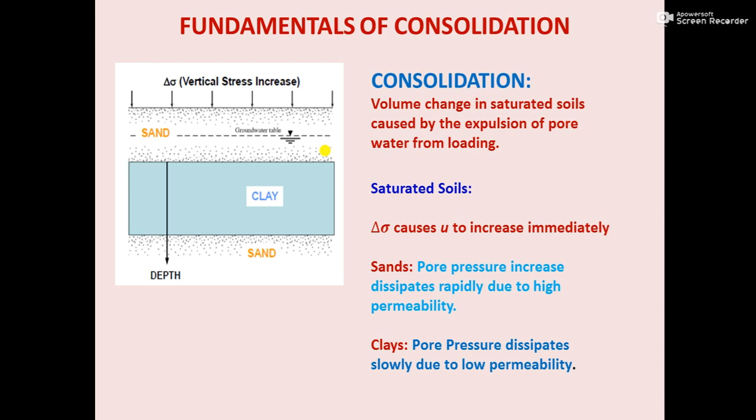So as soon as the pore water needs to take up the pressure, what will happen? Because the water is highly incompressible, the high incompressibility of water will make the water take up the full delta sigma load. So this water will first have to take this delta sigma load, because it cannot move out of the clay soil, so it will have to take the full delta sigma load.